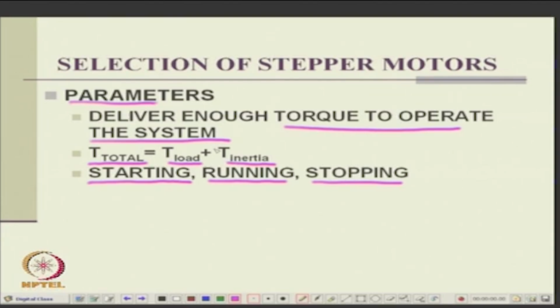Now, where does the inertia torque become predominant in the three modes? Here you have inertia torque, and here you have inertia torque. When it is running, it is just Newton's law of motion, with no disturbance. When it is in continuous motion, all that your accelerator should do is make sure that it takes care of the friction torque, the load torque.